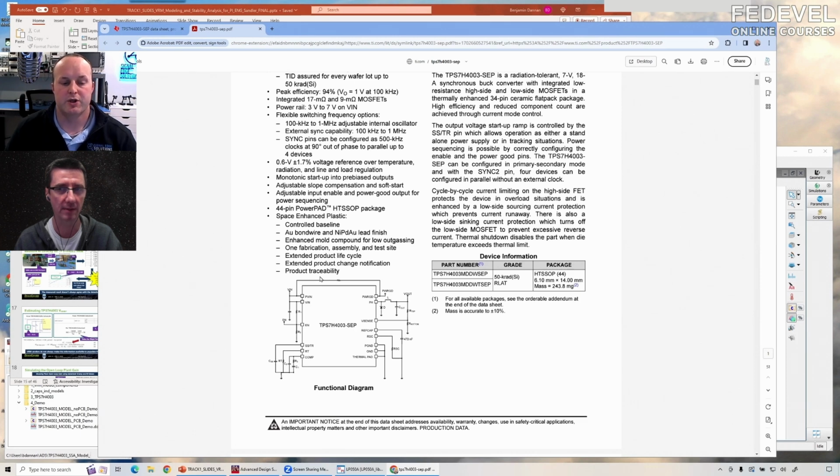Simulation will help us. You can see in real time what your output ripple looks like. You can see your output impedance, your PSRR. You can look at your open loop gain if you want to do that. And then you can see how, with your PDN, all those components are affecting the overall performance of your power supplies from a noise perspective, from a ripple perspective, and then add in your load.